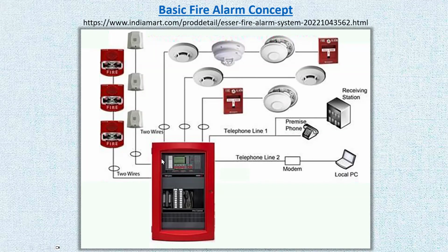And of course, before the annual inspection, the monitoring station has to be notified that, yes, you're going to see a bunch of triggers, a bunch of signals. Please ignore them for the next, let's say, 2 hours, because we're doing an annual inspection. If you don't contact the monitoring station, then if you start triggering devices, you're going to see fire trucks at your door, right? So that's important to contact.